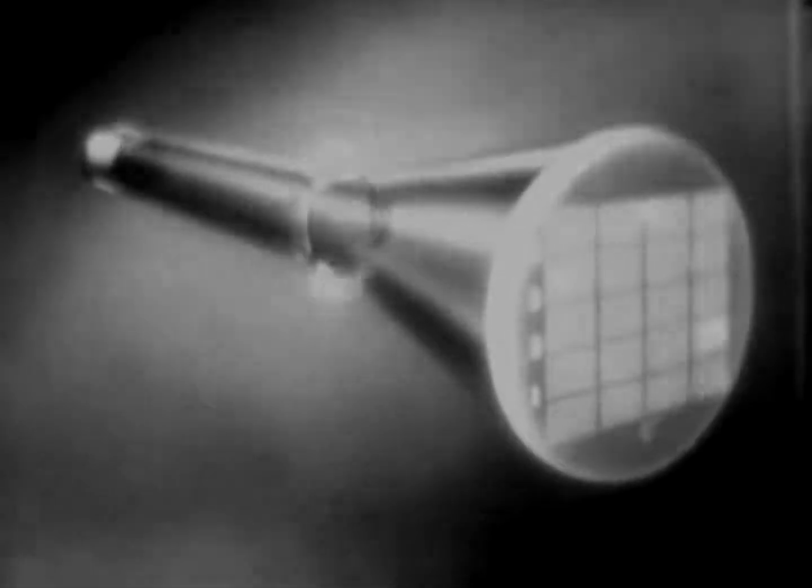Now let's see how the tube does all this. You've already seen how current flowing through the 2 side coils produced the baseline. Varying the current flowing through the top and bottom coils makes the baseline sweep across the face of the scope. The flow of current through these 2 coils is electrically synced with the antenna, so that the baseline always indicates the direction the antenna is pointing.